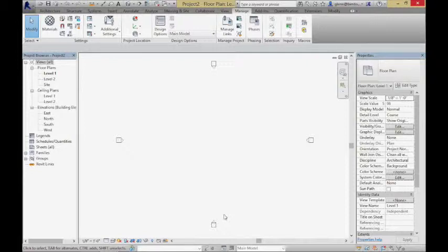What have we done? We've chosen a latitude and a longitude, and this is going to help us understand how high the sun's going to be in the sky at different times of the year. It's also going to help us understand the weather profile. That's very critical as we're designing our building, because of cold weather buildings and warm weather buildings, we have to think about what problem we are solving. Are we needing to heat the building or cool the building, and how intense the sun's effect is going to be?